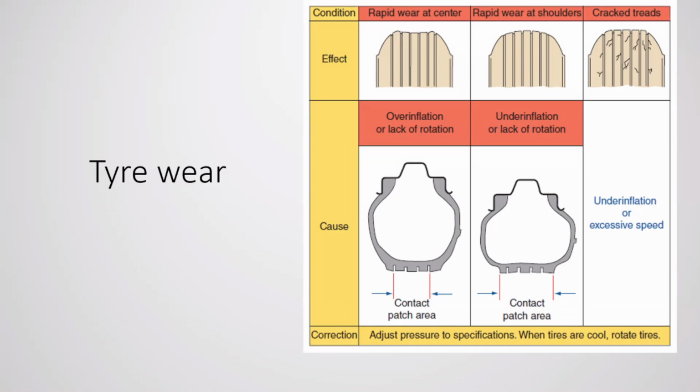If your tires are older than 5 years, even though you still have a good tread pattern, your tires have expired, right? If the manufacturing date is, let's say this is 2025, and your tire manufacturing date is earlier than 2020, which means your tire is expired, right? So the maximum time is 5 years.